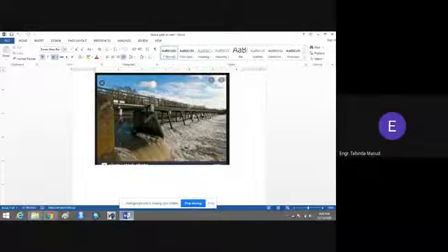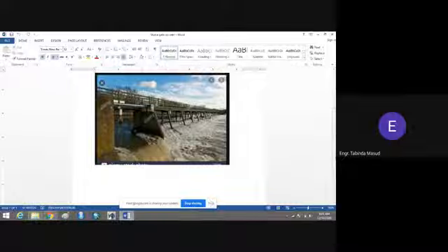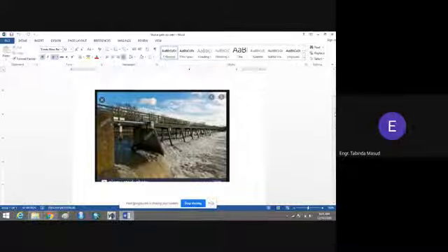For example, on the upstream side you have a tributary and you want to divert water towards the irrigation system, so you need to raise the level of water at the upstream side, for which the sluice gates are closed. The water level is raised and the water is diverted towards the irrigation system. Similarly, sluice gates are also used to raise the level of water for navigation, for sailing ships, etc. There can be different kinds of functions.